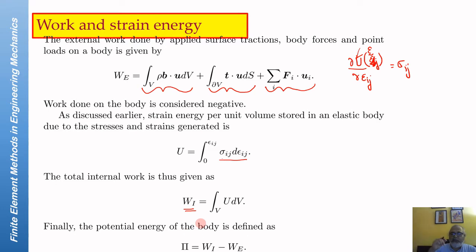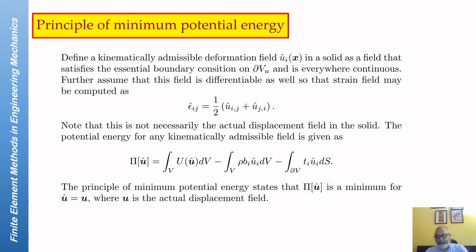And now we come to a very important theorem, the principle of minimum potential energy, which applies to elastic bodies in particular. Imagine that we have defined what is known as a kinematically admissible deformation field. It is a displacement field where all components of displacement are defined at each and every point on the body.